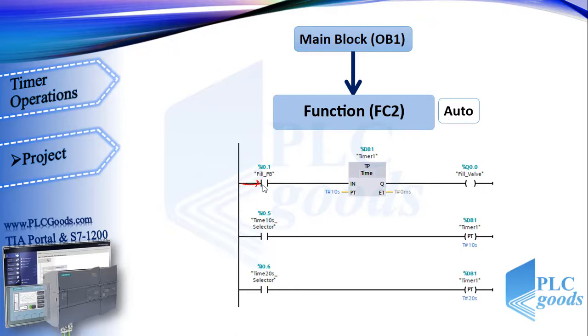In the first line, when the fill push button is pressed, it activates a pulse timer with this preset time. So it turns the fill valve on for a specified time. Also, with the second and third lines, we can change the preset time of this timer to 10 or 20 seconds.